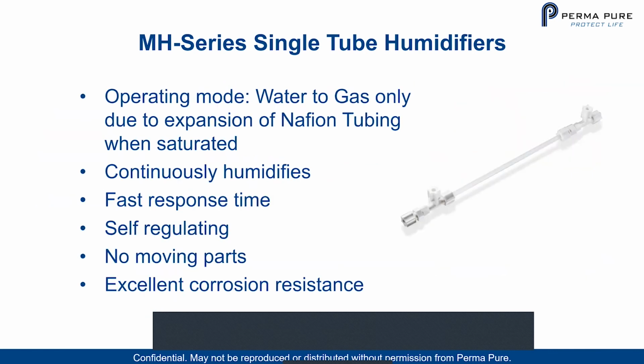So again, the operating mode is water to gas only due to the expansion of the Nafion tubing when saturated. It continuously humidifies. It has a fast response time. It's self-regulating, with no moving parts, and excellent corrosion resistance.